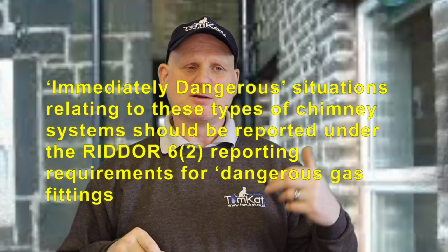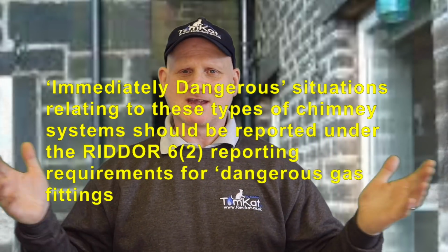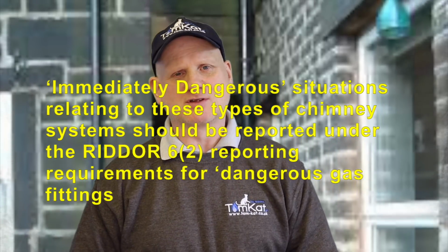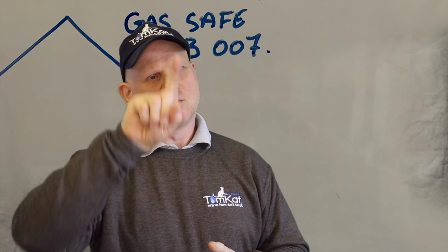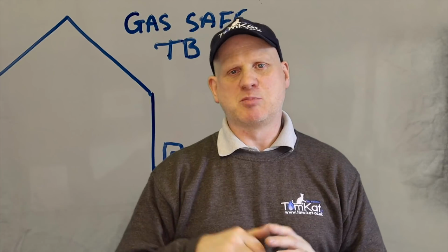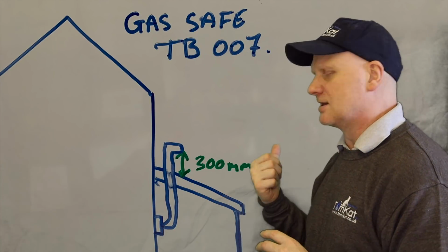Now also, we've just seen carports, flues under carports. Certain manufacturers, Worcester, don't really like you installing flues under carports, and they say you can use your plume management kit to go above the carport. So pretty much like this.